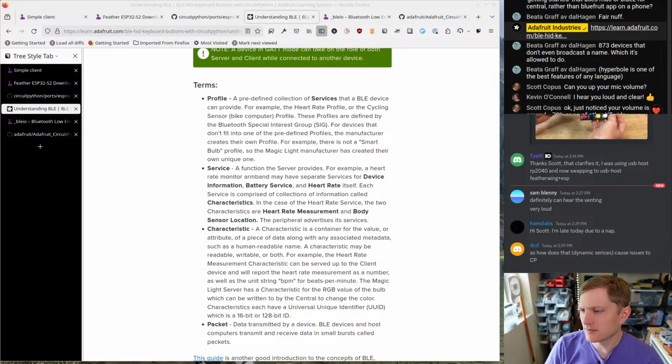DCC asks, how does the lack of dynamic services cause issues for CircuitPython? So the lack of dynamic services was a blocker for CircuitPython, because we start the Bluetooth stack up earlier than when user code runs to define the services that the user code wants to present.